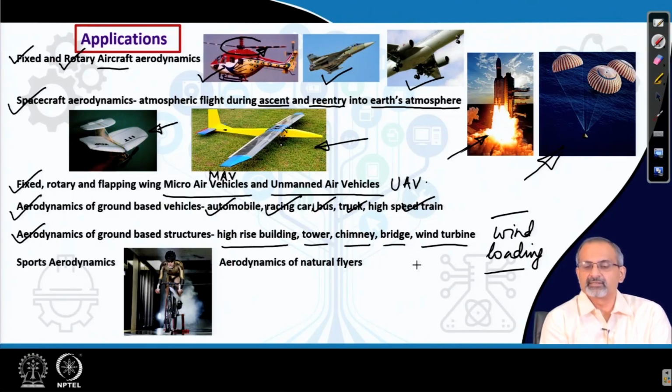Now, the structure of these earth fixed structures could be flexible and they could be responding to the airflow and undergoing deformation. One thing that we have to be very careful about is that they do not get into a very damaging oscillatory mode while the wind moves past them, because there is vortex shedding which occurs from many of these surfaces, and that is basically going to lead to some kind of oscillatory load on these structures, and they can set these structures to a very dangerous mode of oscillation if the frequencies are close to the resonant state.